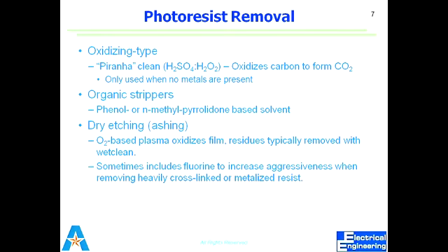They have their own protocol for disposal. So phenol-based solution had the problem that its disposal was very costly, so it was replaced lately by N-methyl pyrrolidone. It also works well, and it can be used to remove the organic strippers, including the photoresist residues.